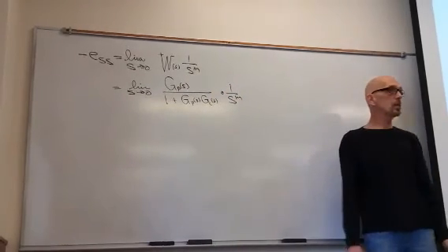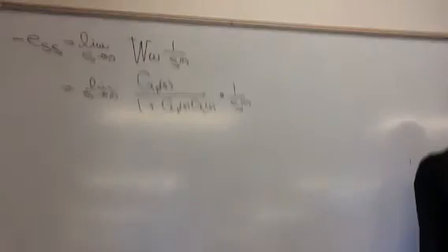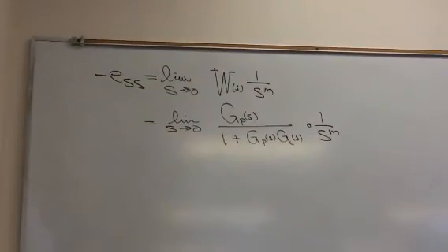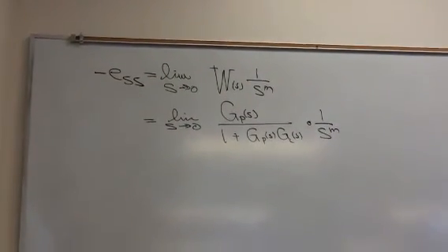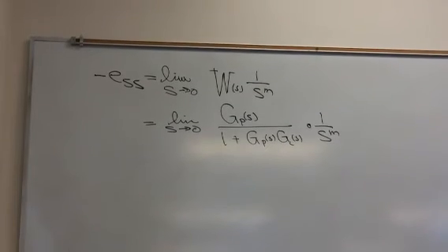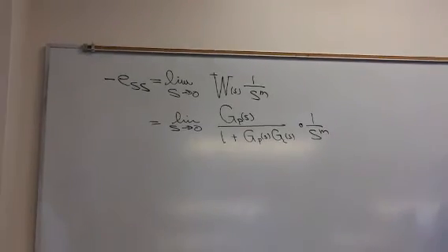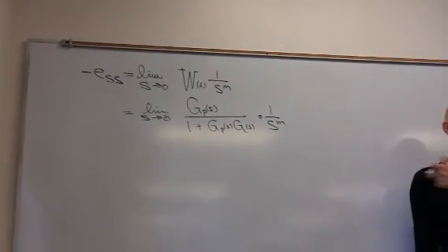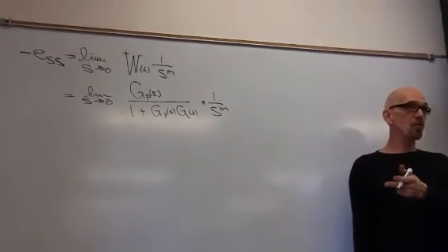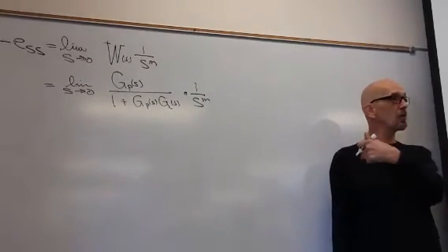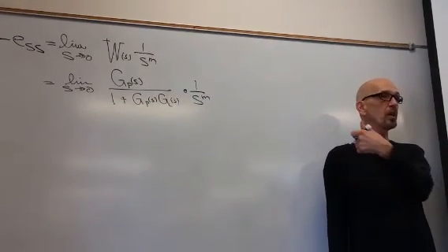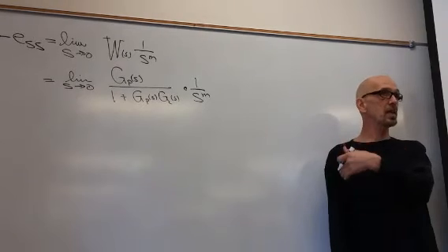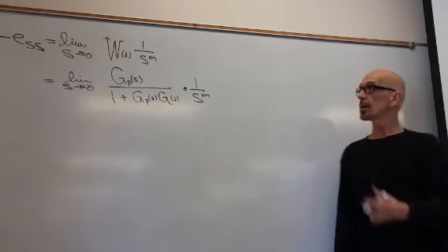So far, so good? You should all know that a feedback system with forward loop G and feedback loop H is G over 1 plus GH. The feedback, we put our controller in the feedback loop. For the reason, aka the block diagram, I want the output of the feedback to be force. I want that force to cancel the input force. And I want the difference in force to be what excites the plant, or the wingtip.